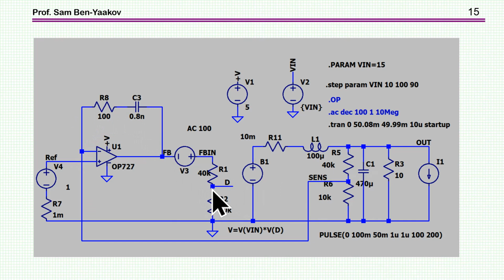This is not a switching signal, but an average value of the duty cycle. And then I have a multiplier of this average duty cycle times Vin, that is the input voltage. So we see here not the pulsating waveform, but rather the average values of these waveforms.